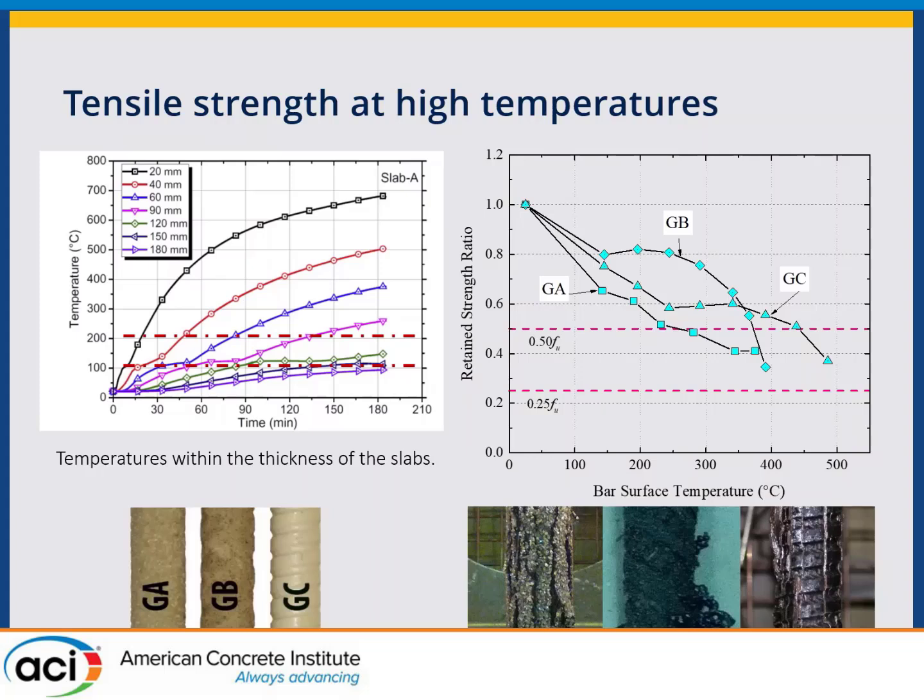So you realize that in a fire, the stresses are going to be at the level of what we restrict in the design code, no more than about 20 to 25 percent sustained stress. So why do we have to have half the strength if we're never going to have that stress present in a fire? So there's one thing.